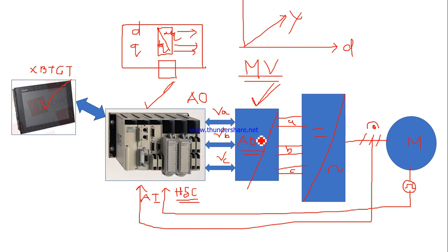For a microcontroller there will be a limitation of output compare timers. There will be 7 timers available in the controller, but once we go for multi-level, the timer requirement is more. In that case we can use a DSP, or a microcontroller core or DSP core with FPGA as peripheral.